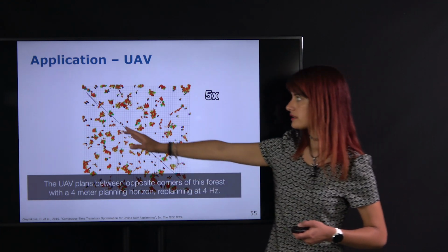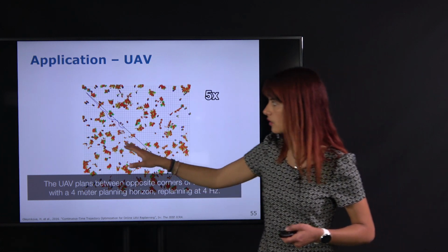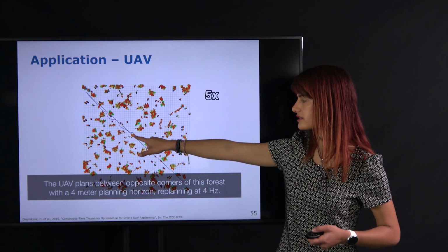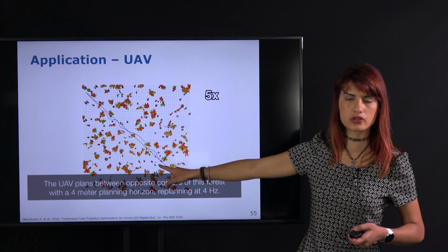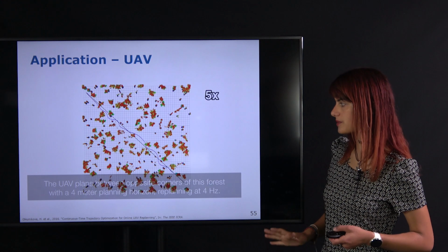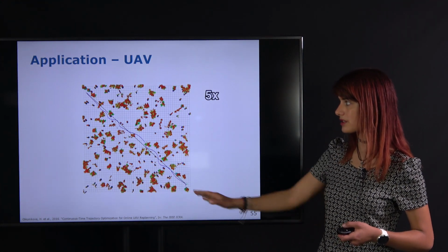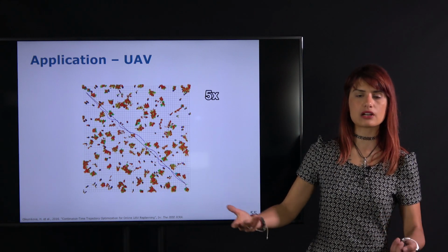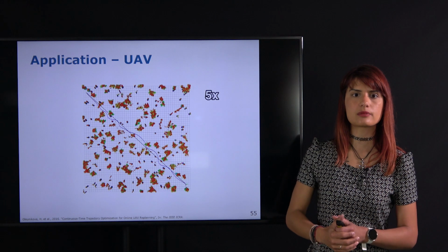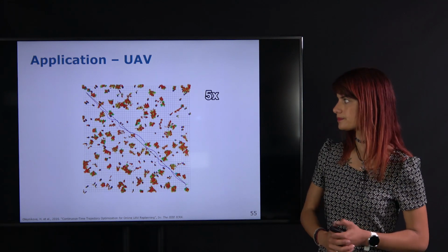Here, the black line is showing the global plan, and in purple we can see the robot following and performing evasive maneuvers to avoid any collisions with the obstacles. This simple example gives us a very good idea of the hierarchy involved when we want to deploy planning algorithms in a full navigation stack on board our robots.